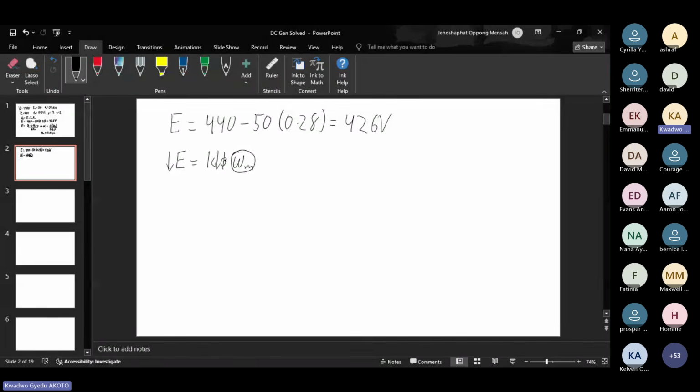But in that instant, we are going to have a reduction in our E for the time being before the speeding up can account for it and keep E constant. So we are treating K as a constant, and we are treating omega m as a constant because it hasn't started to speed up yet. So speed is the same.